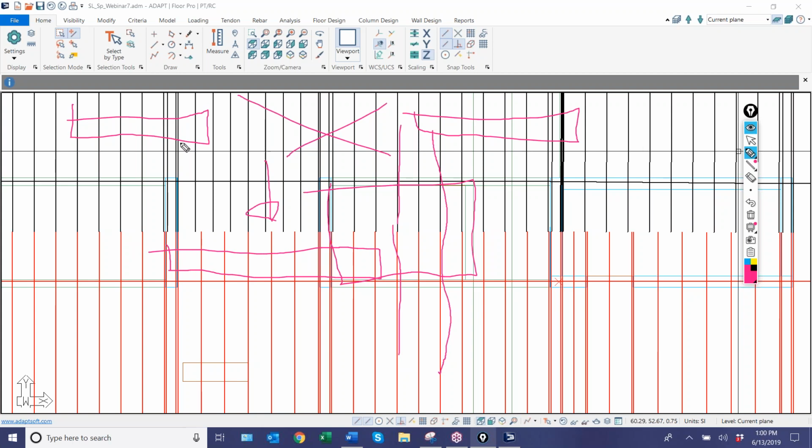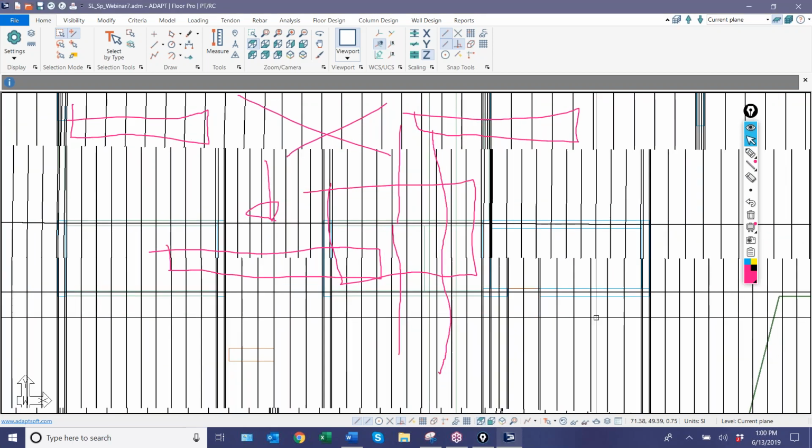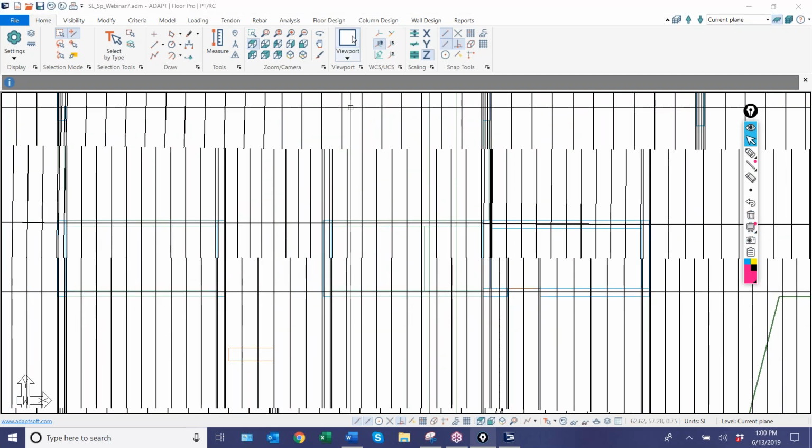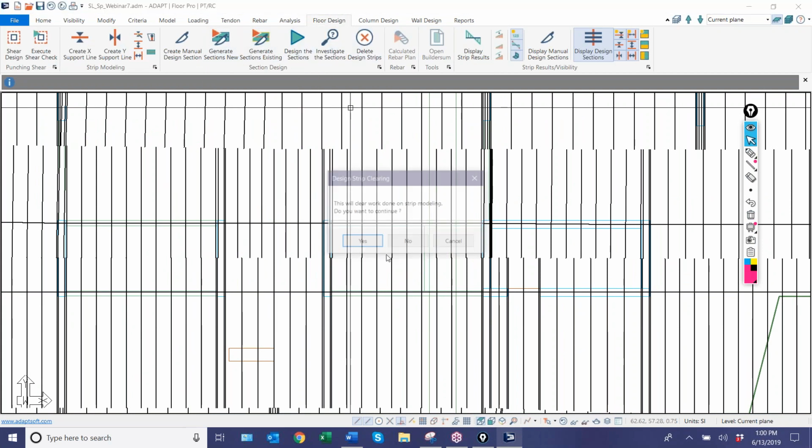So now it's integrating the actions here and here on two sides of an opening and saying, okay, for that integrated and resultant set of forces, shear, moment, axial, whatever is happening at the centroid of this idealized cut, here's the rebar and here's the stress check. And in reality, there's a discontinuity there. So to handle something like this, you have to use splitters to bound off the opening and generate the proper set of design cuts.